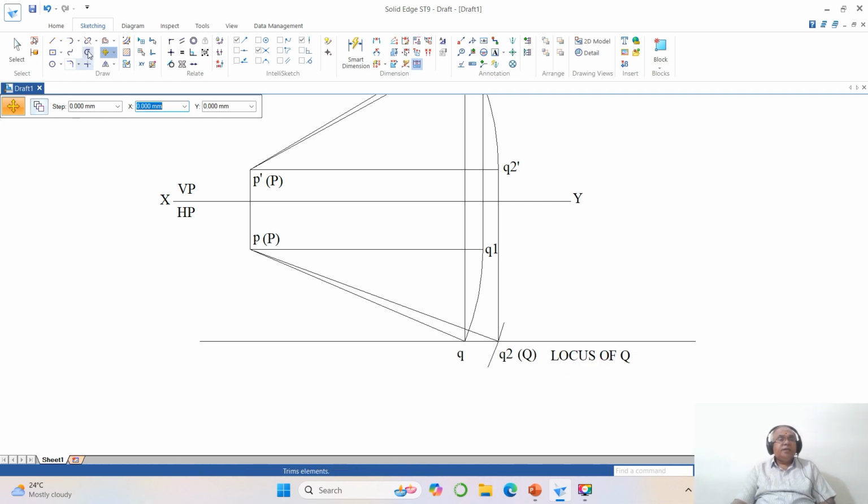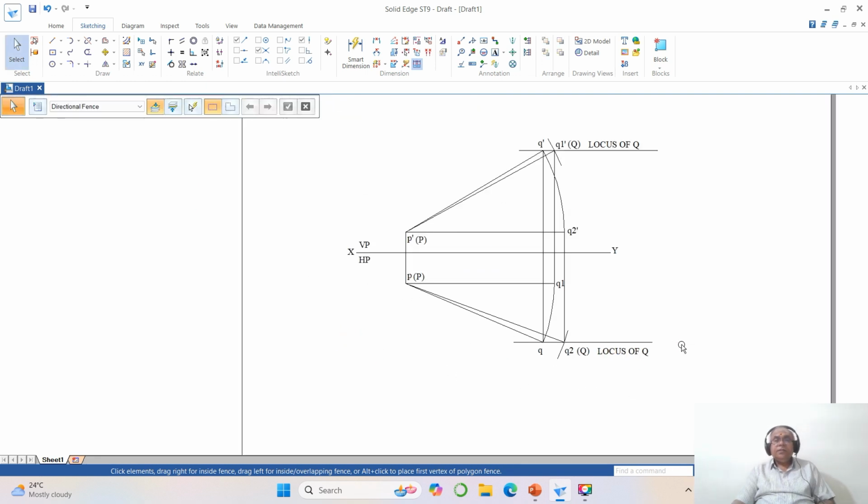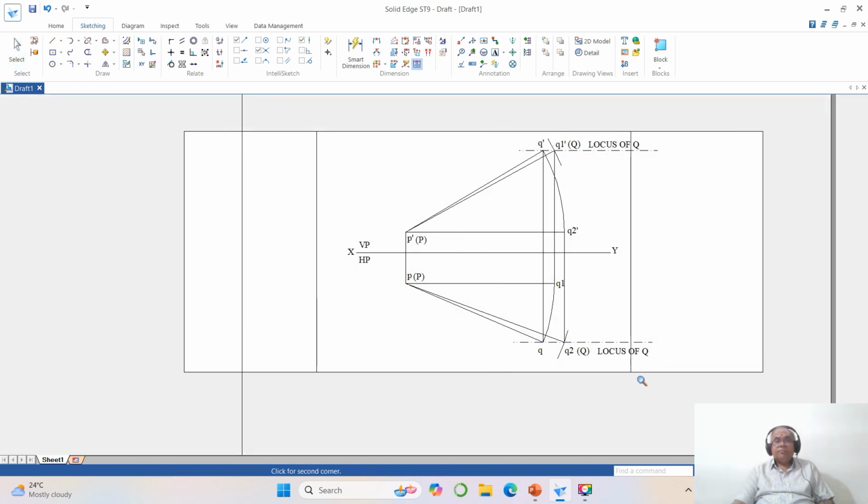So this is how you will be able to create the drawing. Now I want to split this. Similarly, I want to split this till here. Then go to shift, select this, and you select this and remove it. Similarly, on both the sides we have done, you take these two. So change the line type to dash dot. Then come down to zoom window.